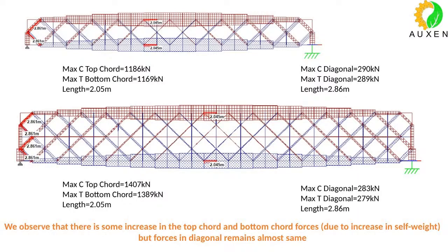So that is the advantage of Bailey that you get, that you can actually design a Bailey's module and you can repeat it, you can stack one over the other, and you can use them for multiple configurations. Okay, so this flexibility and freedom you do not get in the K type. So the K type bridge does not offer you this flexibility which Bailey's bridge offers.